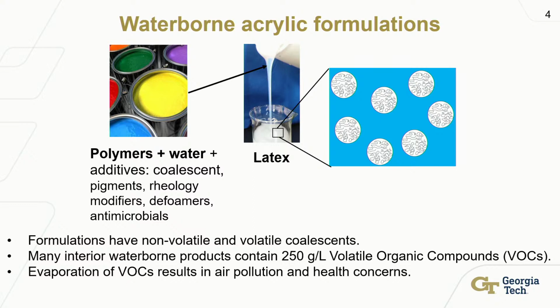And most of these formulations have both non-volatile and volatile coalescents in them. The coalescent's job is, they partition into the latex and they keep it soft so that when it forms a film, the particles are nice and soft and can fuse together.